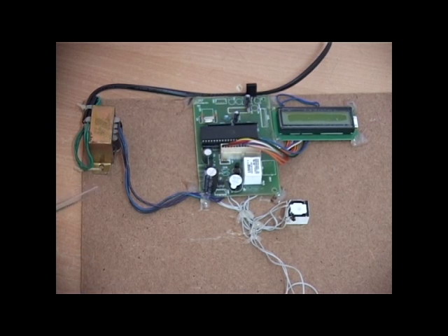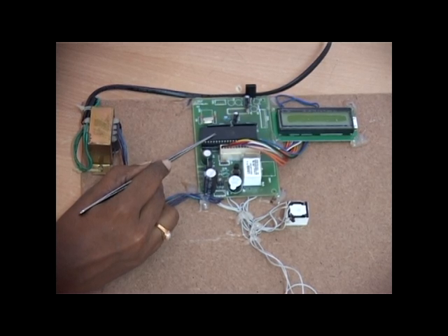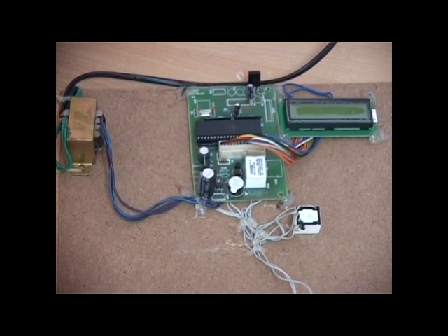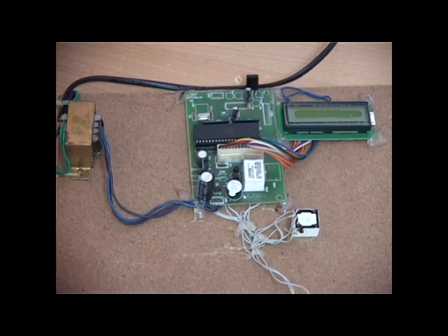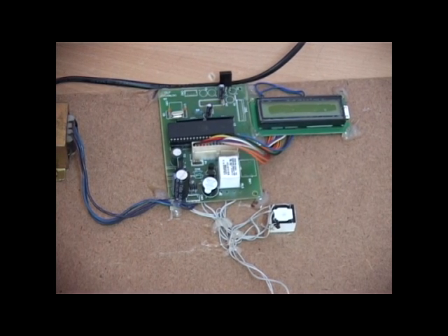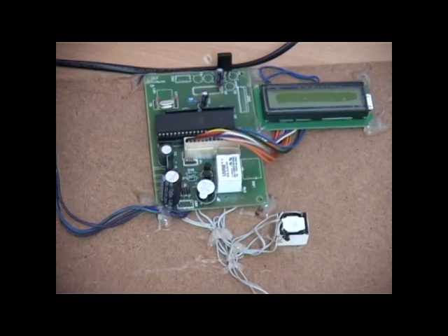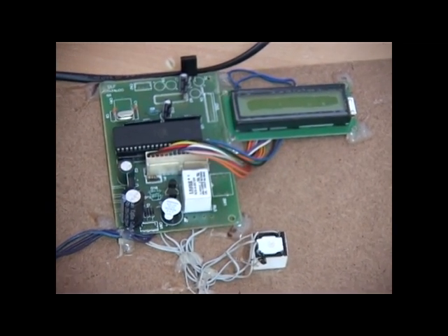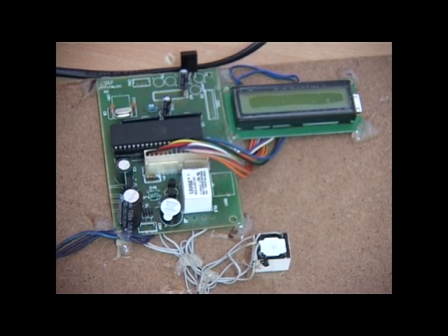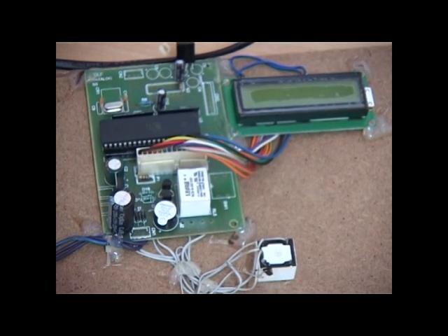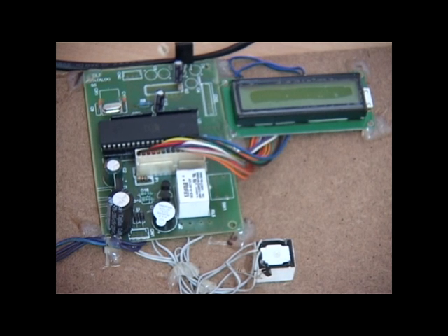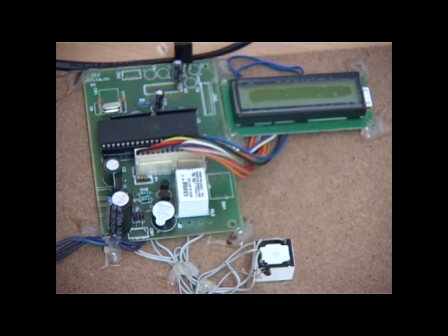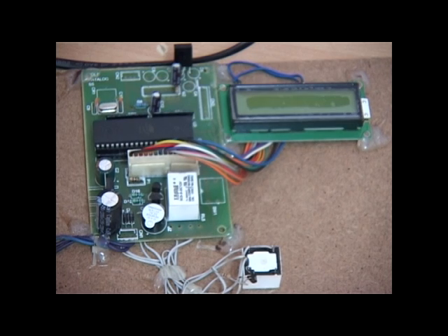The microcontroller receives IR data from the RxD pin, and the received data is accumulated in the serial buffer of the microcontroller. The data is compared with the predefined codes 00, 01, 02. If the code received by the IR receiver equals 00, then the motor will be stopped. If the code received equals 01, we apply low voltage to the motor, and thus the speed of the train is controlled and it travels at low speed. If the code equals 02, then the motor rotates at full speed and we apply 3 volts.